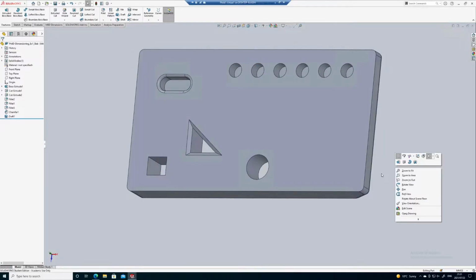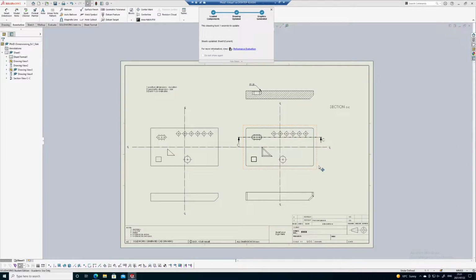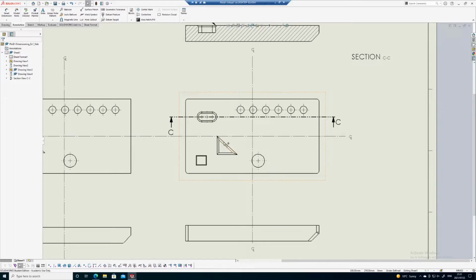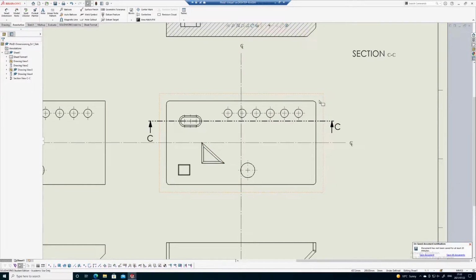When we hop over to the drawing, it's pretty much the same thing, that you need to think of dimensioning, which is what we just did in the first lesson. You need to think of dimensioning in terms of the basic shapes, and then the added bits and pieces like the edge radii, tapers, chamfers, corner radii.